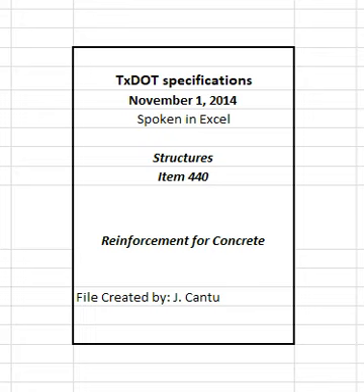3.7 Handling and placing stainless reinforcing steel. Handle, cut, and place stainless reinforcing steel bar using tools that are not used on carbon steel. Do not use carbon steel tools, chains, slings, etc. when handling stainless steel. Use only nylon or polypropylene slings. Cut stainless steel reinforcing using shears, saws, abrasive cut-off wheels, or torches.